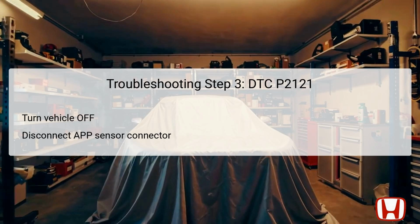The next task involves measuring the voltage between the specified test points in the APP sensor connector once the vehicle is switched back to the on mode. It is vital to ensure that approximately 5.0 volts is registered as expected. Achieving this reading indicates proper power supply to the sensor, permitting the troubleshooting process to continue towards determining any faults present in the circuit.